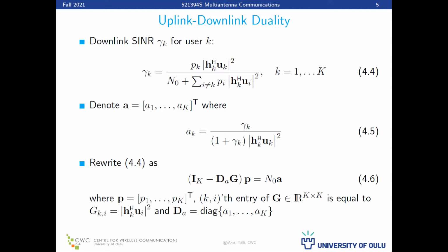The expectation goes inside, and we know that the expectation of D_k times its complex conjugate is 1. This is the normalized transmitted data symbol. So this is equivalent to, okay, we have D_k missing here, D_k goes here. So we have P_k times |H_k Hermitian u_k| squared. And then similarly for the denominator, we get all these terms, the interference terms and noise.